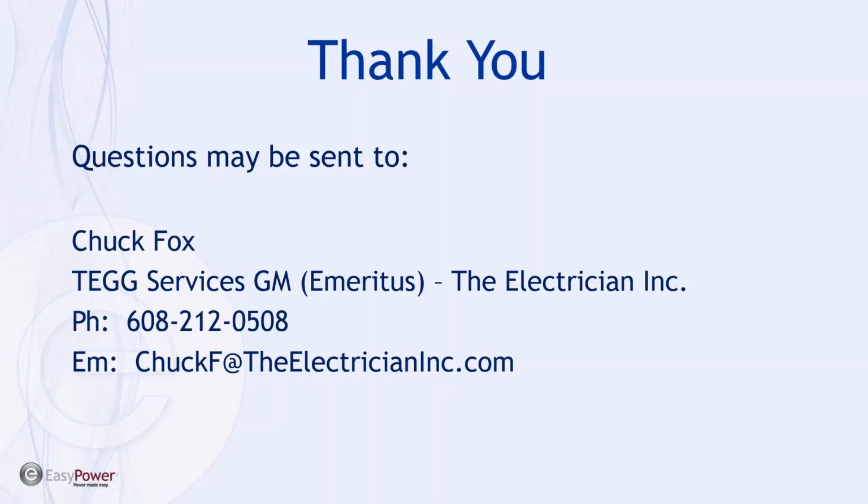With regard to testing, again, infrared specifically is recognized as one of the fundamental tests. The next piece of that is there's other tests out there that can provide, I'm going to say, advanced levels of testing. One great example is on most electronic breakers today. The electronic trip setting modules themselves have testing ports that you can bring in a protocol called secondary injection testing. Transformers, you could hook up meters and do transformer turns ratio testing.